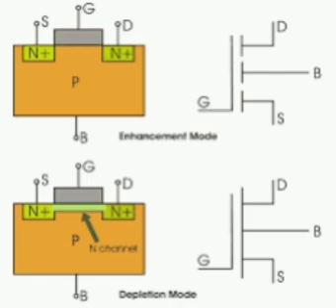It is used as a linear device as well as a negative resistance device. Best material is gallium arsenide having highest swing. It is used in designing microwave oscillators or as a relaxation oscillator in designing of pulse and switching circuits and as a parametric amplifier.